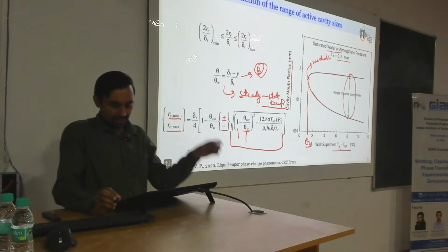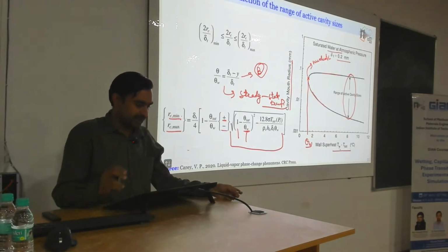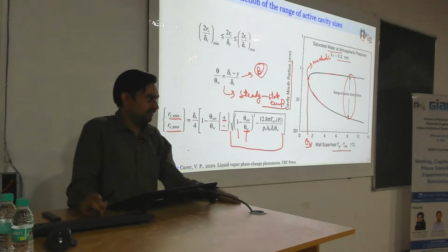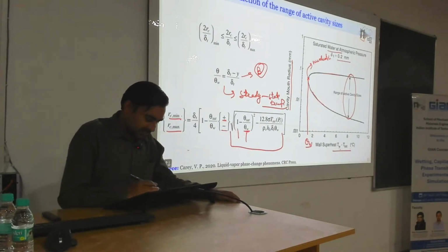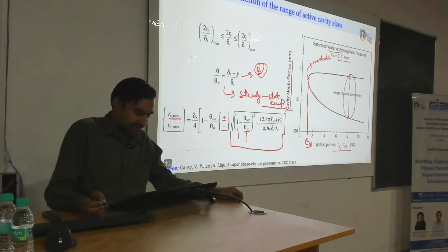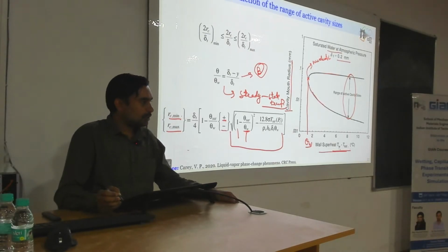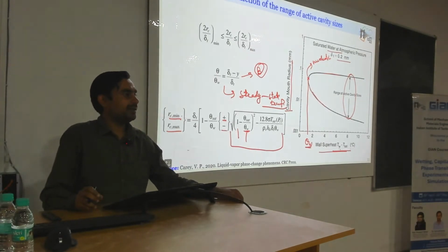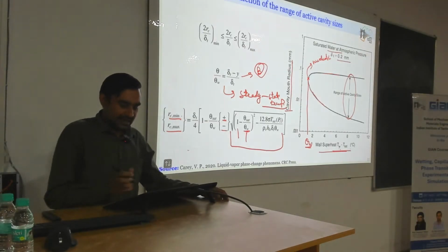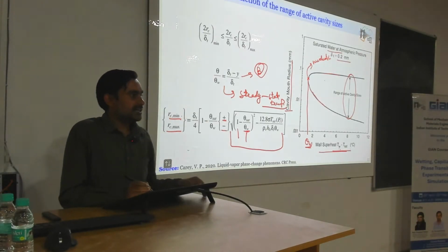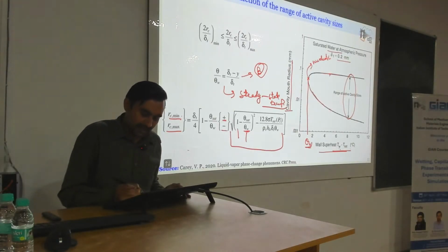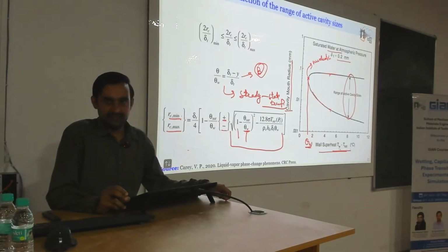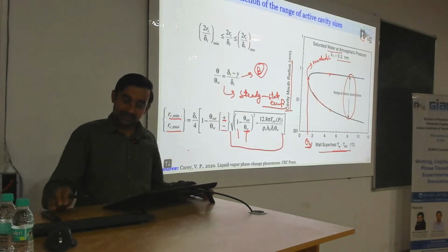We started our discussion on nucleation from cavities and onset of nucleate boiling in the previous session, and part of it is left that we will now continue. If you recall, this was the last curve where we left. We had cavity mouth radius as a function of the wall superheat, and we found that a minimum amount of wall superheat is required for the cavity to be active. As we increase the wall superheat, we find a spectrum between the minimum and maximum value of the cavity mouth radius, which will be acting as the active nucleation sites.